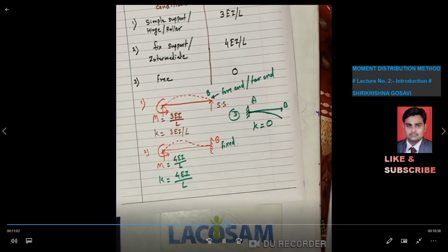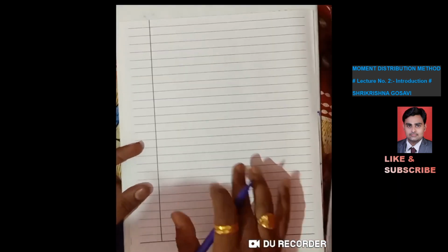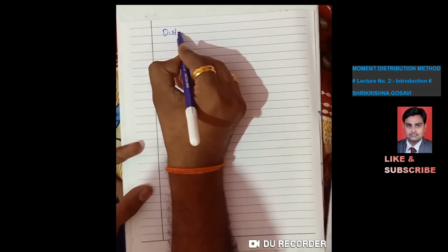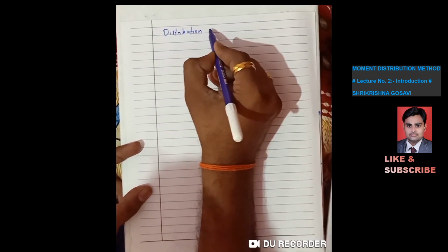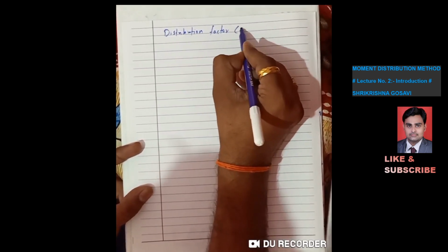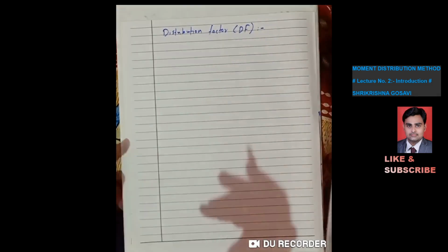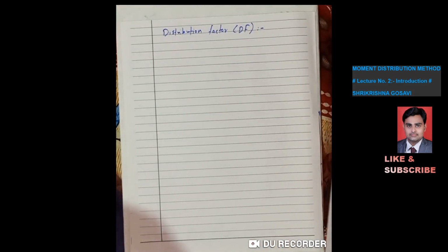After this, the next part is distribution factor, DF. The distribution factor for a member at a joint is the ratio of the stiffness factor of a member divided by the total stiffness of all the members meeting at a joint.